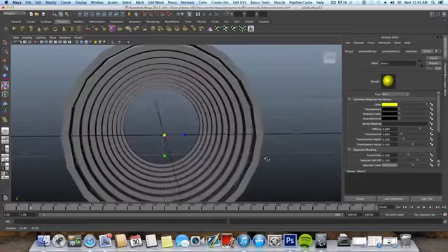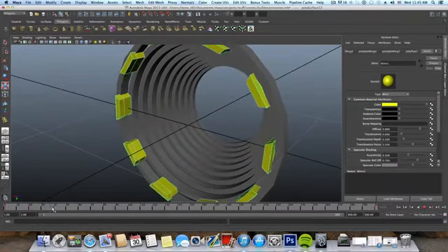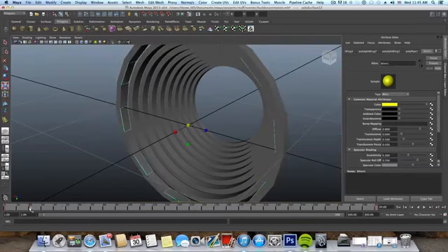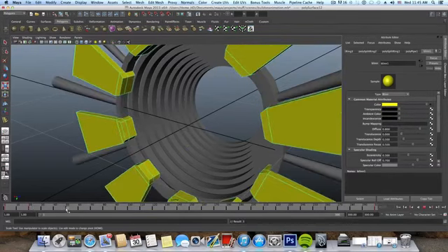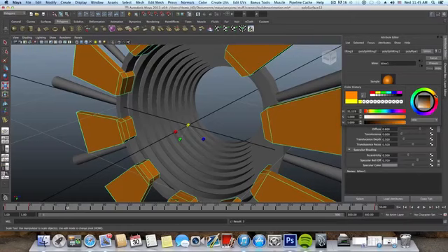Now in frame number 20, where they are appearing, I want this to be yellow, so I will right click on the color and choose set key. So now they are yellow. If in 50 I want them to be kind of orange, I will change the color to orange first, and right click on color, set key, and you can continue this.